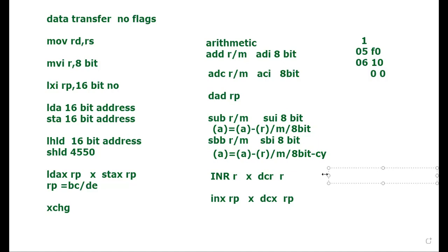In this case, INR or DCR, the carry is not affected. All flags are affected except carry. INX or DCX instruction will affect no flags. No flags are affected by INX and DCX instruction.